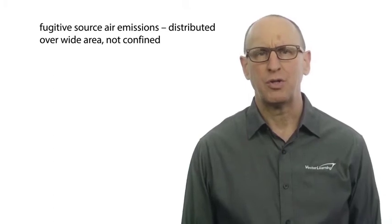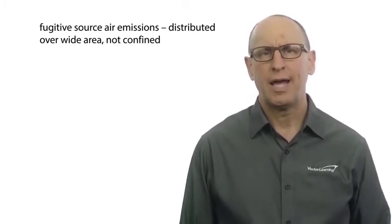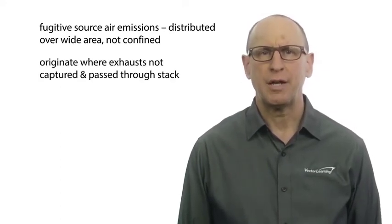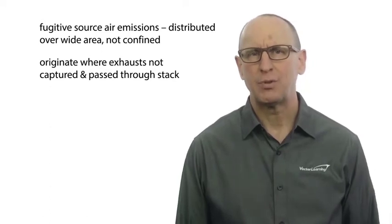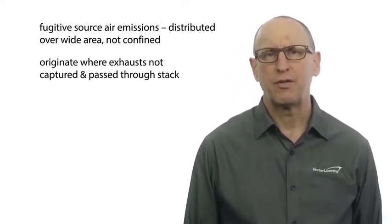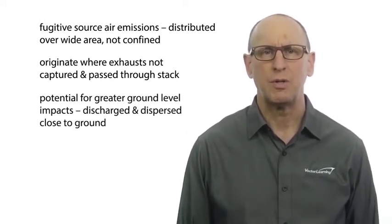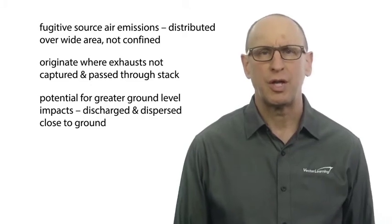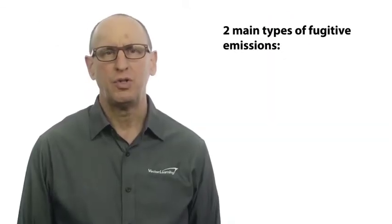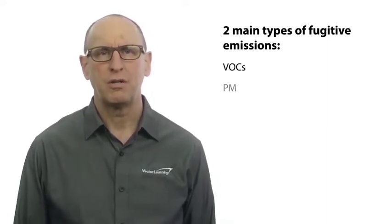Fugitive source air emissions refer to emissions that are distributed over a wide area and not confined to a specific discharge point. So they originate in operations where exhausts are not captured and pass through a stack. Fugitive emissions have the potential for much greater ground level impacts than stationary source emissions, since they're discharged and dispersed close to the ground. The two main types of fugitive emissions are volatile organic compounds, VOCs, and particulate matter, PM.